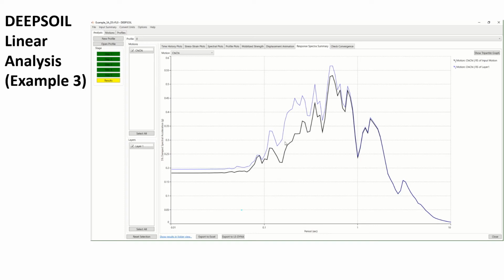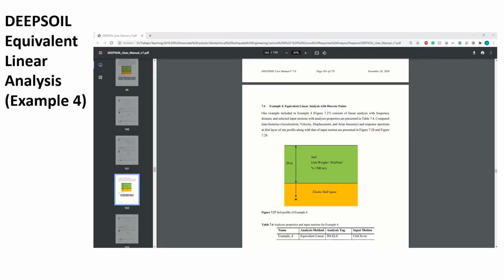It's going to be impossible, if not very difficult, to see that this value is going to be below the input motion, because we always say that when there's the transmission between the superficial soil layers, there's normally an amplification. So the idea would be to minimize that amplification by obviously using different types of geotechnical infrastructure or wave scattering dissipation. But the objective, or the ideal condition, would be that this amplification is reduced to the minimum between the input motion and the soil surface layer.